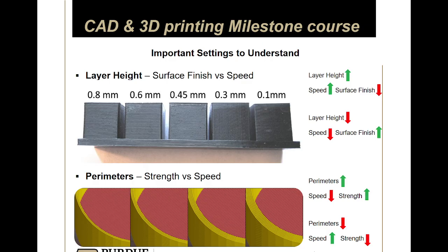One thing to note is that 3D prints typically fail along the Z-axis, right? And it's because the bond between each layer isn't as strong as the bond within the material itself. So that's usually a weak point. So if you want a mechanically strong part, sometimes increasing the layer height will actually make the part stronger, because there are fewer points of failure for the part to shear along the Z-axis. So if you want a really strong mechanical component, some people recommend you increase your layer height to be a little bit coarser. That's just some interesting information for you.